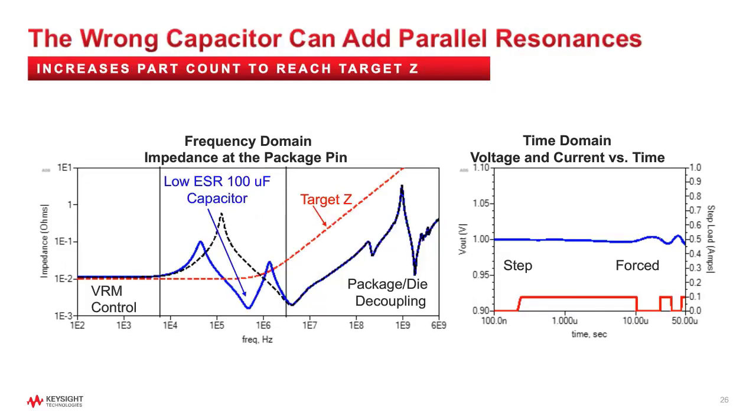If one simply adds a factor of 10 capacitor, like a 100 microfarad capacitor that a datasheet may recommend, or that was leveraged from a previous design, the impedance peak that was causing the power rail noise ripple can be reduced from the original dashed black trace to that of the blue trace. However, notice that by adding this wrong capacitor value, two more resonant peaks have shown up. The bulk capacitor is the wrong value for flat impedance, and the first peak shows that it is resonating with the VRM inductance. The second, higher frequency peak is the capacitor's ESL resonating with the package die capacitance.